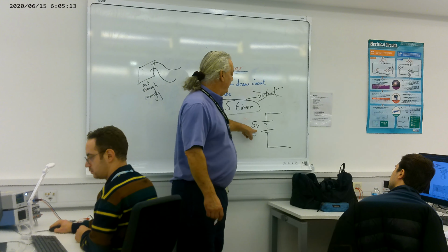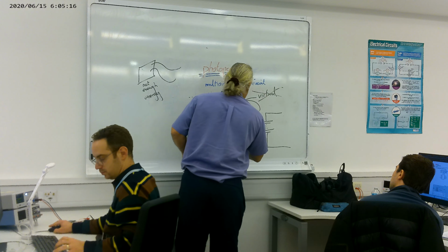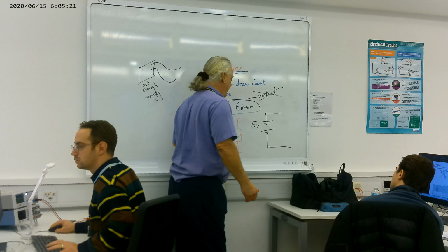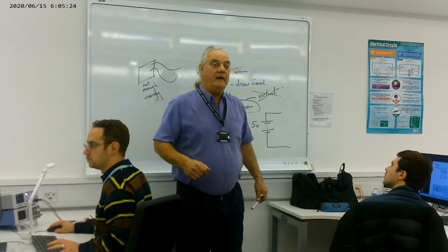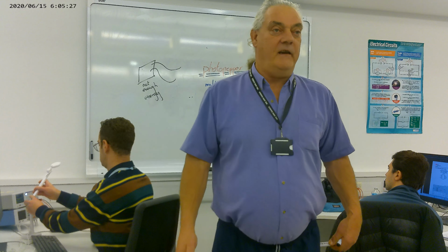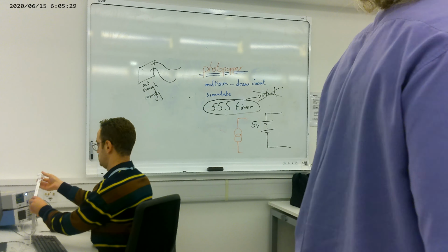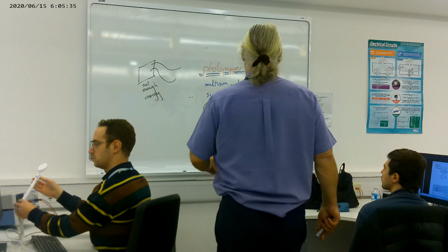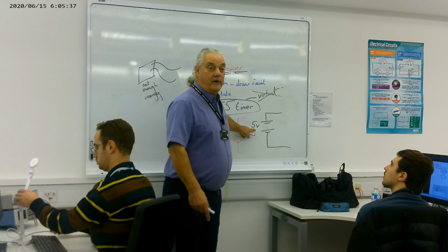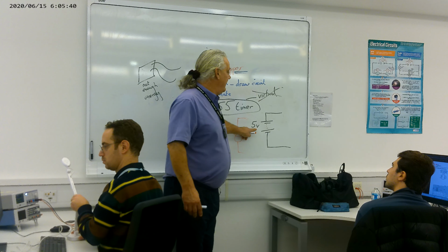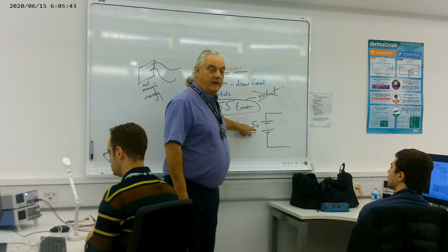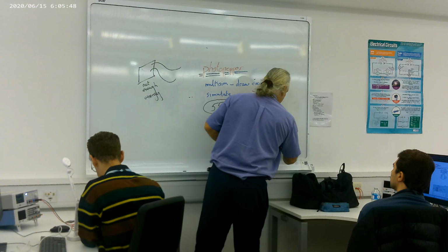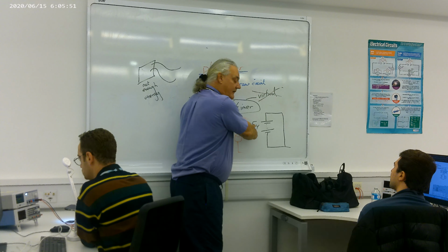Because all that battery says, and it would have this general form if you were going into complex circuit analysis, is that I could drive anything with it. Why can I drive anything with it? That's silly, it's only 5 volts. But it can drive infinite current. There's no current restriction on this. I haven't said it's 5 volt 1 amp, then I'm suddenly restricting it a little bit. All I've said is that it will deliver 5 volts. Well, if I put a short circuit in here, this will still drive 5 volts.